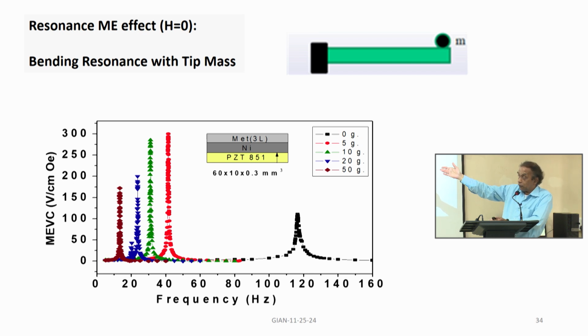So the field that you want to measure will appear as sideband around the resonance at that particular frequency. So all you do is measure the height of the sidebands that you can relate to the field that you want to measure. It's rather easy. You have to have a calibration curve relating known field to the voltage, then unknown field you can measure easily.